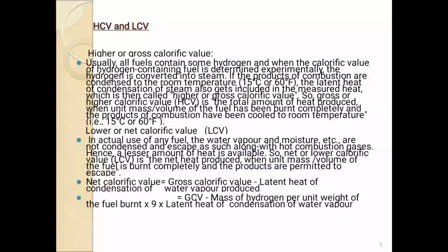Then lower or net calorific value. In actual use of any fuel, the water vapor and moisture are not condensed and escape as such along with hot combustion gases. Hence, a lesser amount of heat is available. So, net or lower calorific value is the net heat produced when unit mass of the fuel is burned completely and the products are permitted to escape. Net calorific value is equal to gross calorific value minus latent heat of condensation of water vapor produced, which is equal to GCV minus mass of hydrogen per unit weight of the fuel burnt into 9 into latent heat of condensation of water.